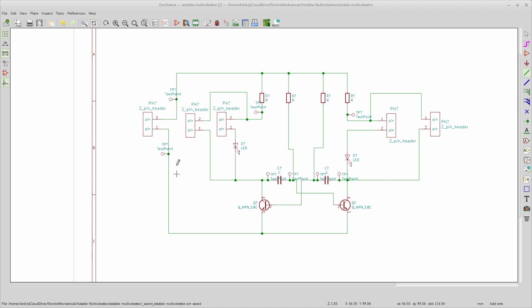To go over the test points first, you put your positive and negative here, so we can check voltage there, or I can have a ground point to clip onto and then be able to probe wherever I want. I have a test point here just prior to this mess, which will be for either an output or just checking voltage before the LED, I guess.